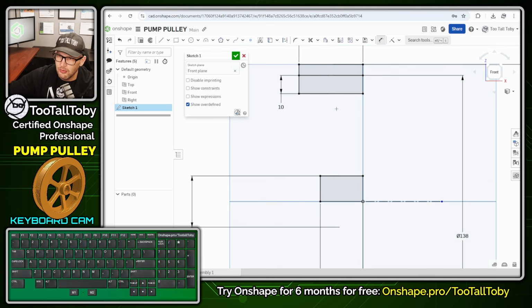We're going to do this with two lines. So S key line, you can single click here, move your mouse up, single click. You can just hit escape and then S key line again. And for the second line, we're going to single click here, move our mouse. We're going to put our mouse over the first line. See, right now, if I move this mouse around, it's just kind of out in space. But if we put our mouse over that first line and then move out in this direction again, you'll see that you can pick up on a relationship of parallel.